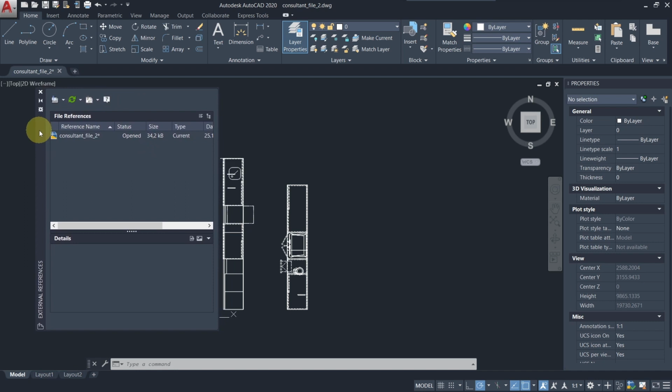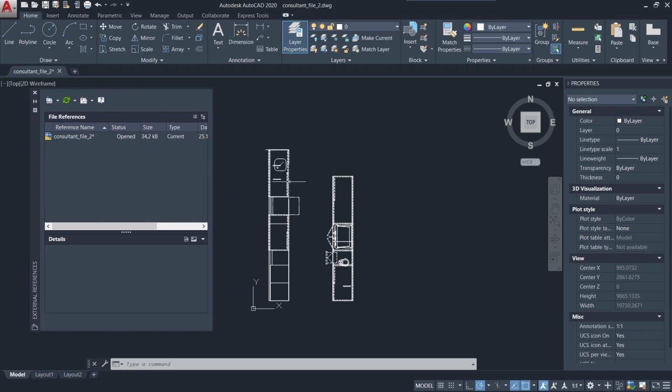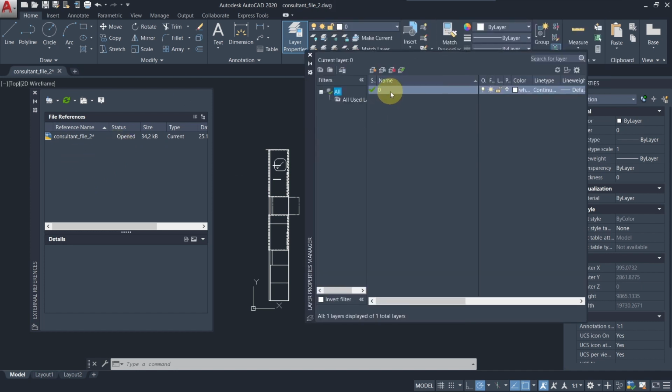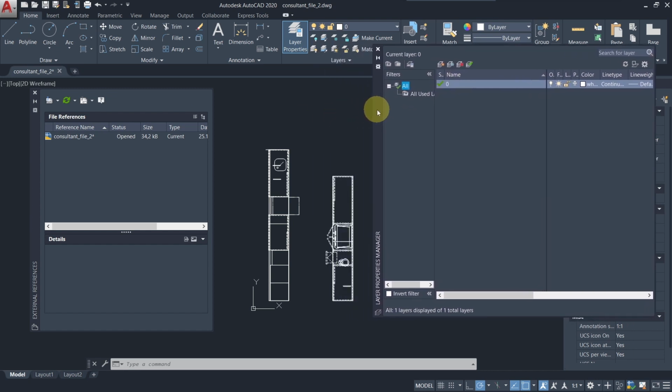So you should always try to clean your DWG files in the way that it will be as small as possible without any external references. All the geometry will be placed only on one layer, and there will be only one layer. You should purge all. Sometimes flatten, audit, remove overlapping lines, so use overkill.